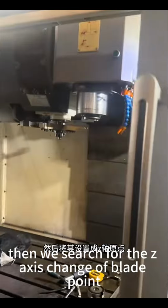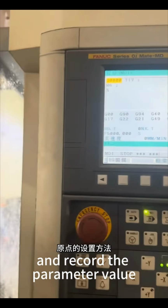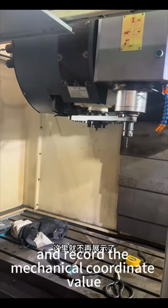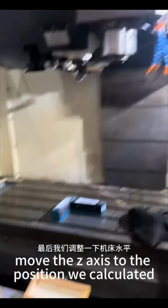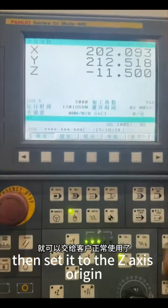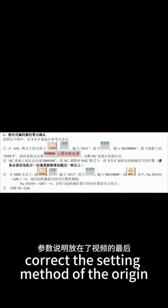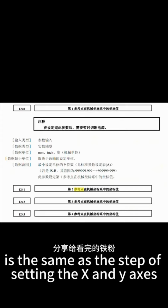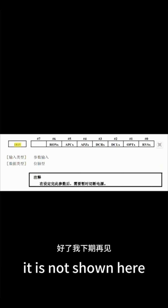Then we search for the Z-axis tool change point parameter 1241 and record the parameter value. Then look at the current machine coordinate position and record the machine coordinate value. Then you can calculate the origin position. Move the Z-axis to the position we calculated. Then set it as the Z-axis origin. This can ensure that the tool change point is correct. The setting method of the origin is the same as the steps for setting the X and Y axis in the front. It is not shown here. After setting